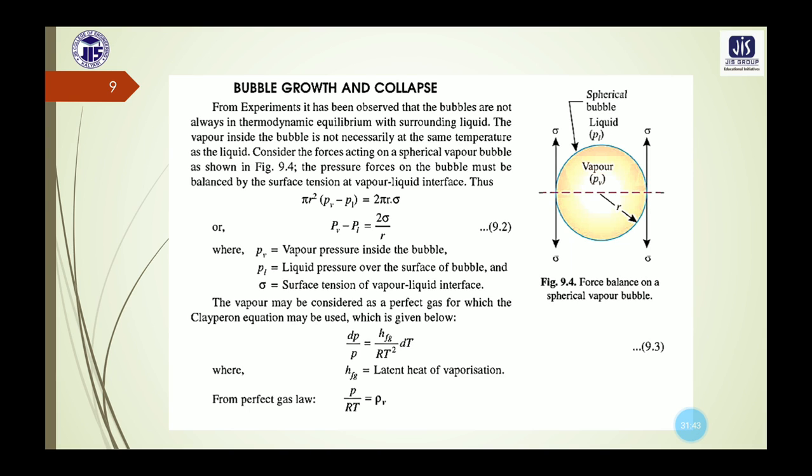Let's discuss the bubble growth and collapse. From different experiments, it has been observed that the bubbles are not always in thermodynamic equilibrium with the surrounding liquid. The vapor inside the bubble is not necessarily at the same temperature as the liquid.